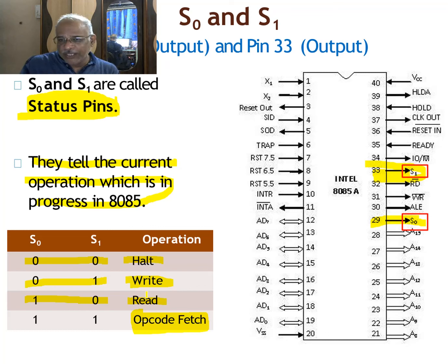How is it given to the microprocessor? Remember, the microprocessor cannot read the opcodes from my paper. So the microprocessor will read those operation codes in the form of ones and zeros only, though I have stored those instructions in the form of hexadecimal numbers. But there is an assembler which will convert those hexadecimal numbers into a particular binary pattern of an 8-bit number. So I will have to store those operation codes.